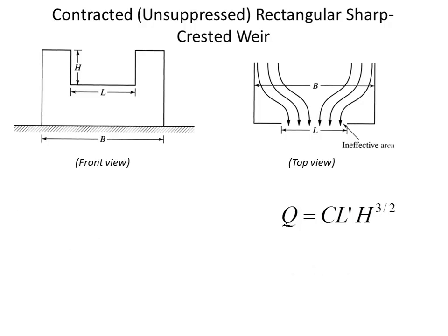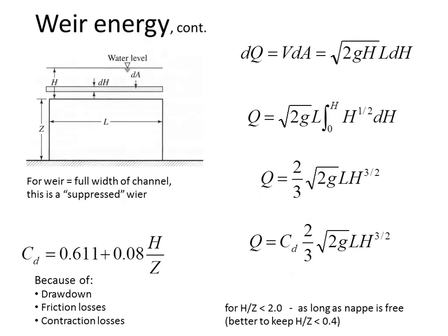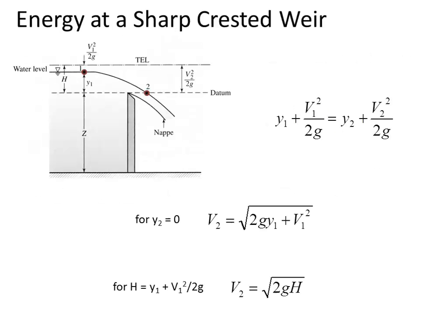One thing that's interesting is that in a weir, this nappe, it's called a nappe, the water that flows over the weir is kind of like a sheet of water. Air can get trapped underneath the nappe. There can actually be a vacuum under the nappe, because when the water starts to flow over the edge, when it's just a trickle,